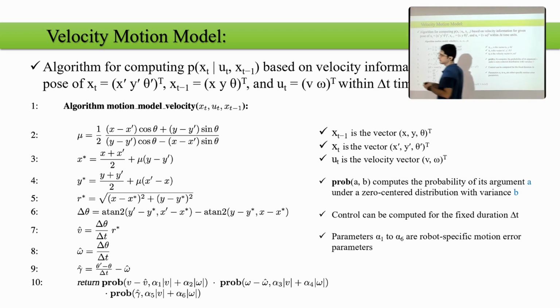We say, okay, the v and w are constant during delta t. They are not changing. Because if they're changing, it ruins everything. You need to include it, or you can break it down into small time steps, so that you can calculate between those time steps that the speed is not changing, kind of discretizing it.